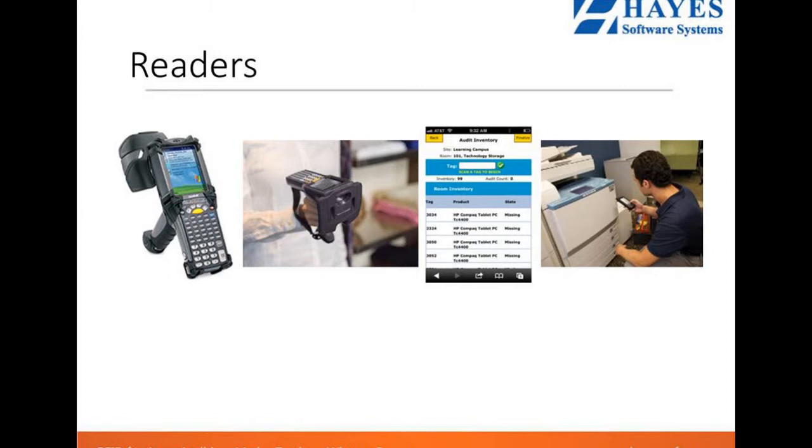An RFID reader is really that device that provides the connection between the tag data and your enterprise system software that needs that inventory information. The reader communicates with tags that are within its field of operation, capable of performing any number of tasks, including simple continuous inventorying and even filtering, so searching for tags that meet certain criteria. All of that's based on the software installed on the reader itself. The reader uses an attached antenna that's capable of capturing that tag information.